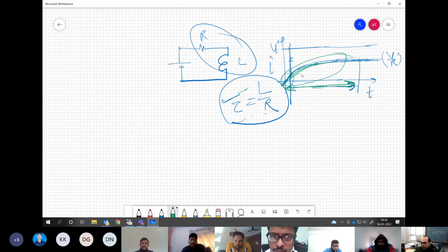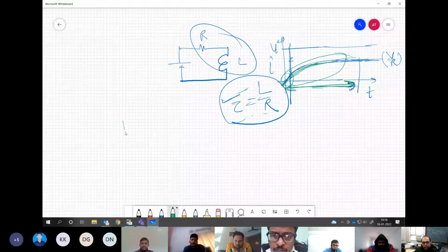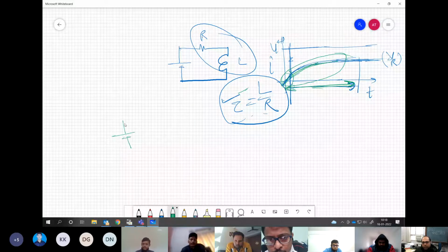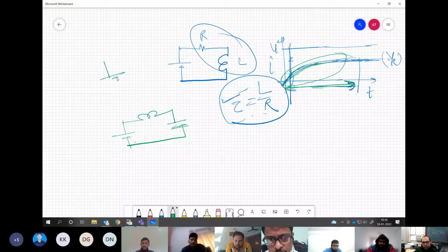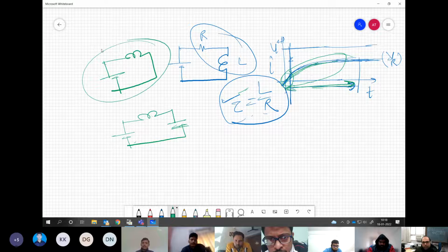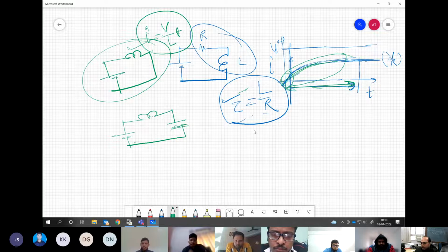This is one reason. The second reason is that we are having constant voltage applied across the inductor. The resistance value for an inductor that we connect in the circuit is very small. So eventually what we see is basically a voltage applied across an inductor, and this is always going to be linear. V by L times T is the current, if you start from the beginning. So these are the two reasons why we have this linear kind of current for the inductor. Fine.